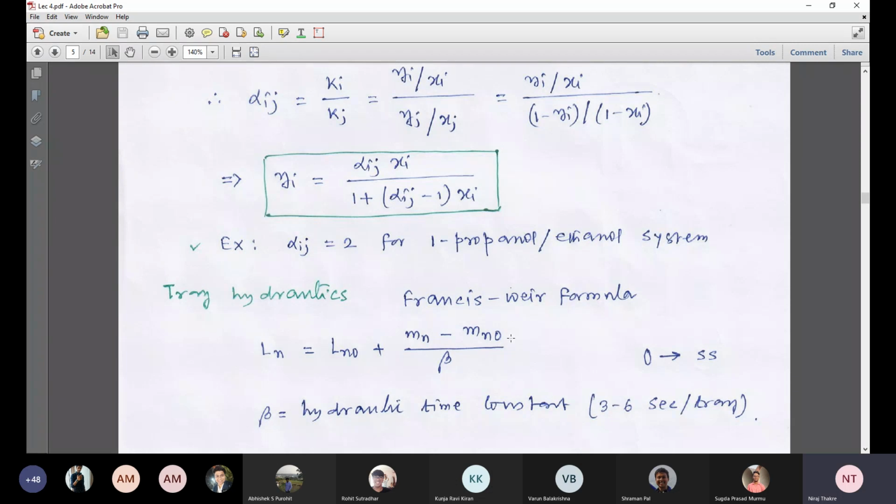Diameter of the tray must be known to you if you design the column. Height of the tray, that is nothing but the weir height. Weir height is in standard dimension, usually it is 1 inch, or maximum 2 inch, which is for a very few cases. It is true for the industrial columns. So height is also known.